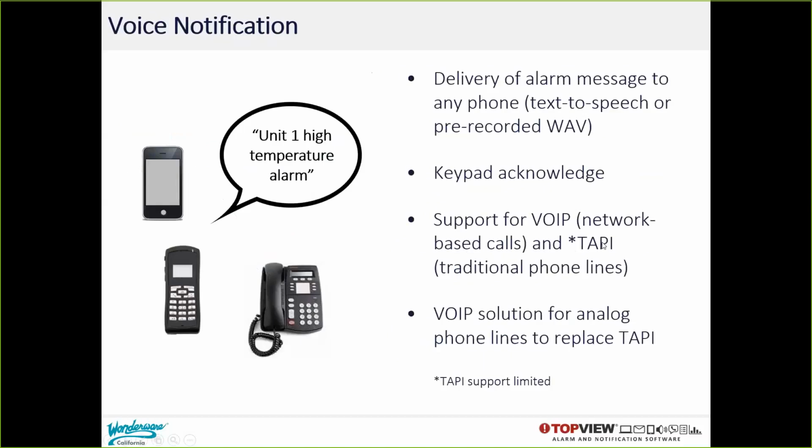Voice notification or voice call out delivers spoken alarm messages to any phone with the ability for the recipient to acknowledge the alarm using the phone keypad. Although we've supported TAPI in the past, we are recommending and moving our users to a more reliable network-based calling through VoIP. Our VoIP solutions could be the customer's in-house phone system if it supports VoIP, like a Cisco phone system. It can be a hosted or cloud-based VoIP provider if you can get to the cloud server.